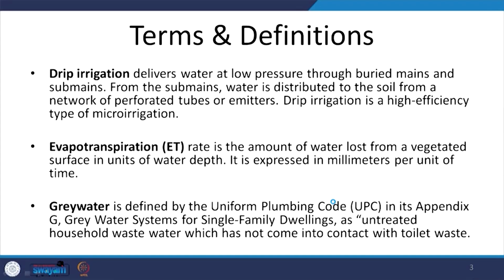Fortunately, the water which is required for irrigation is not potable. Even treated grey water or captured rainwater can very conveniently be used for irrigation without much filtration or treatment, because it is non-potable use. However, even when we can do that, we have to reduce the requirement for irrigation. So, today we will be talking about water efficient landscaping. Before we go over it, let us quickly look at some of the terms and definitions which we will be using in today's lecture.